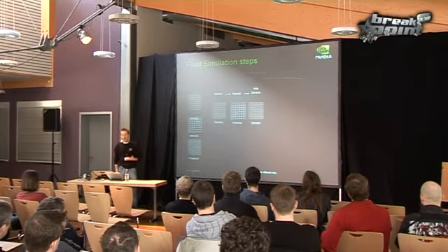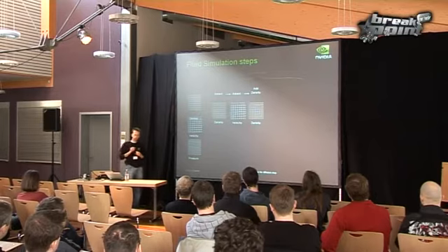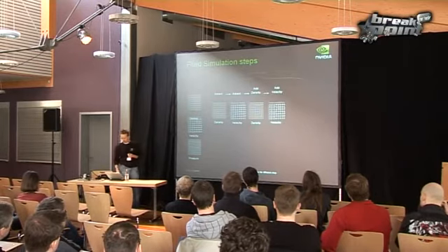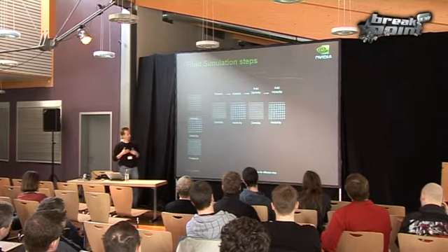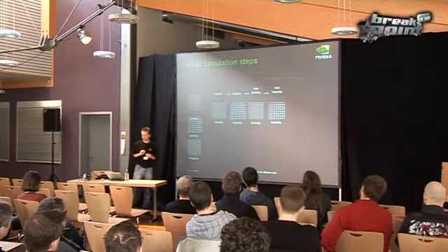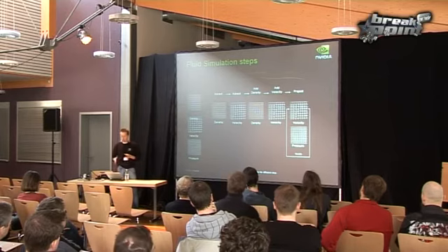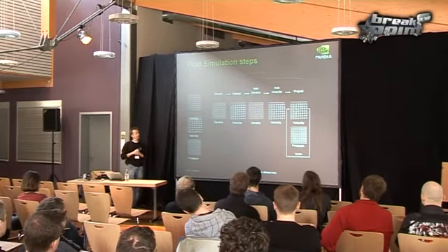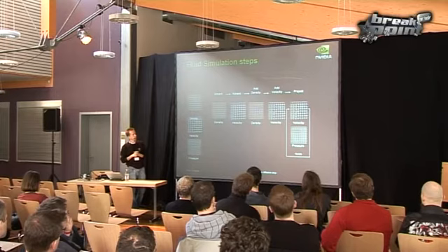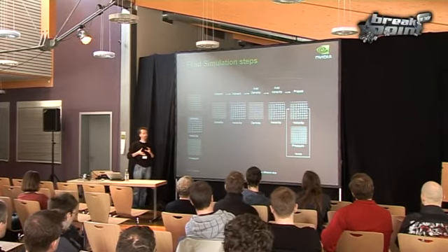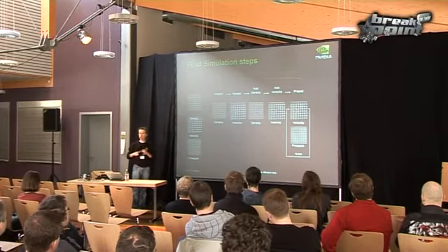Then we can add density to our simulation, so we can inject smoke or fluid. We can add velocity, so when we inject something, we can give it an initial velocity. And then the last sub-step is called project, which means we need to ensure that our velocity field is divergence free and the mass is being conserved.